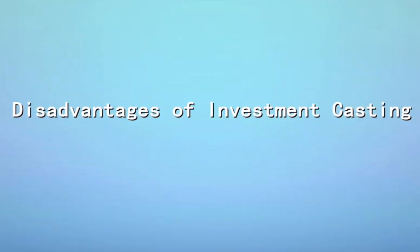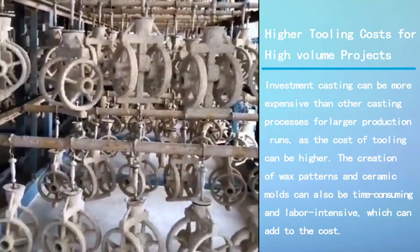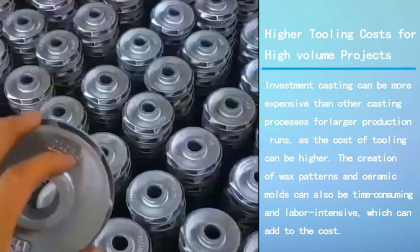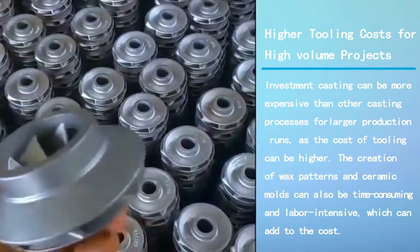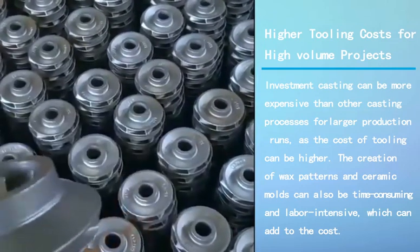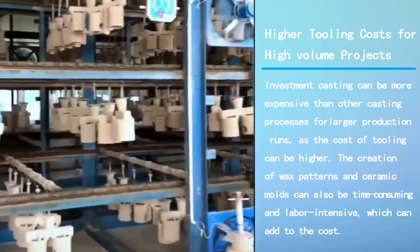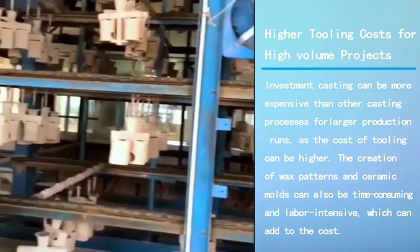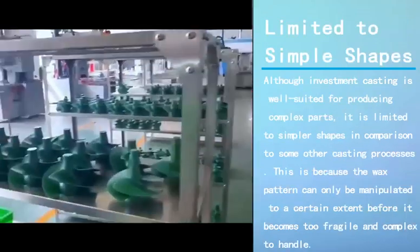Disadvantages of investment casting. Higher tooling costs for high-volume projects. Investment casting can be more expensive than other casting processes for larger production runs, as the cost of tooling can be higher. The creation of wax patterns and ceramic molds can also be time-consuming and labor-intensive, which can add to the cost.